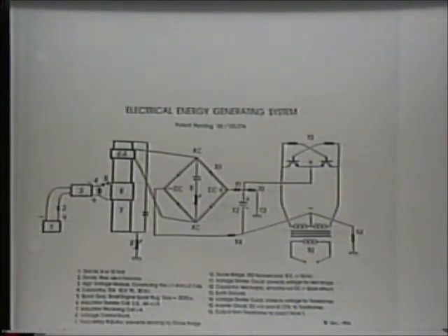Basically what you have is your 12-volt battery. You have a diode which serves to protect the laser module from a kickback. This is a high voltage laser module, and you have a capacitor in parallel there, and then it goes into your L1 coil and then comes back. There's a spark gap which helps control the energy level that's passing. The spacing on the spark gap will control the energy level of the energy that's going into your L1 coil. Then, of course, number 7 is your L2 coil, and number 6A up there is Tesla's third coil.